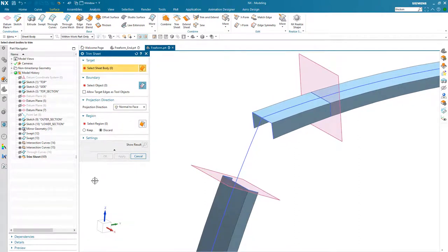And this once again is parametrically recorded. So if you don't like that, you can go ahead and select other types of surfaces or types of faces that you want to use for trimming instead of this particular datum plane. So now same thing, let's go ahead and select this one, and then what is my boundary? Once again, many things that we can use to select: body faces, datum planes, and all that kind of stuff. So in this case, we have datum plane.